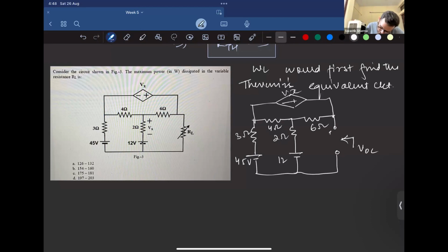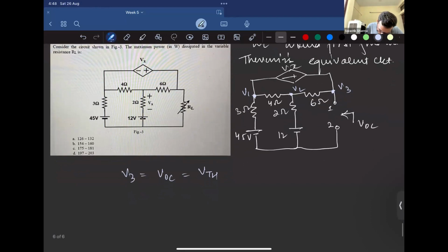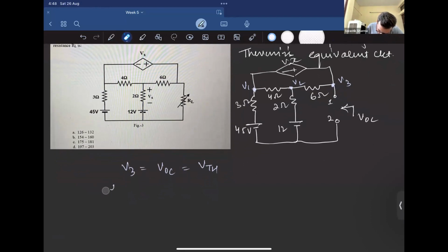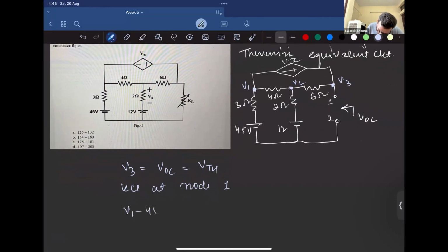So we need to find the open circuit voltage around these two terminals, right? So this is V1, this is V2, and this is V3. Now V3 is nothing but VOC, which in a way is Thevenin's voltage. So KCL at node 1. What would it be? V1 minus 45 by... V1 minus V2 by 4 plus...